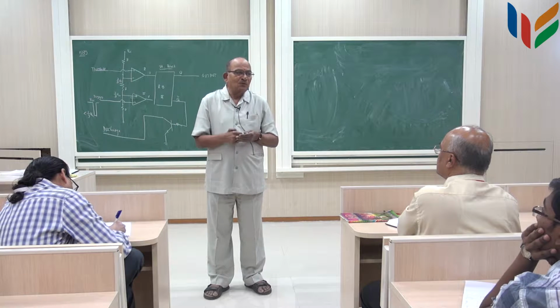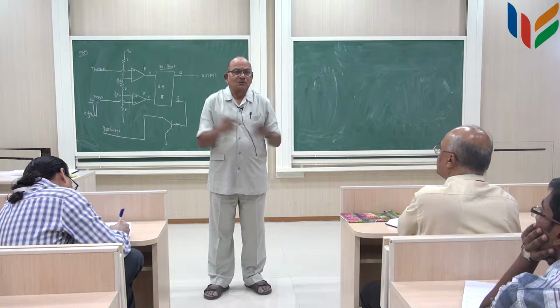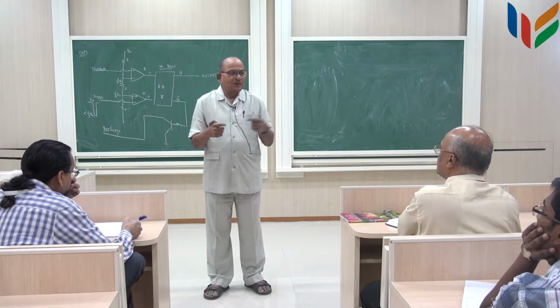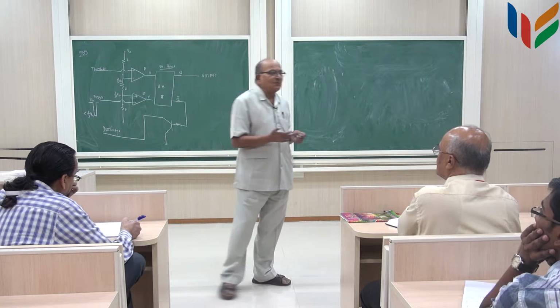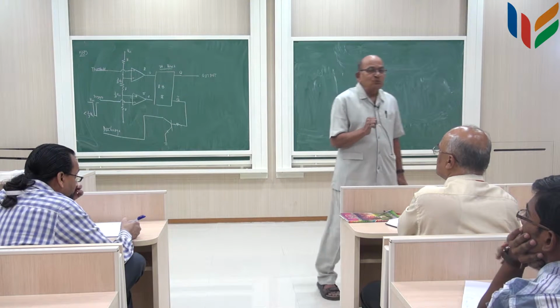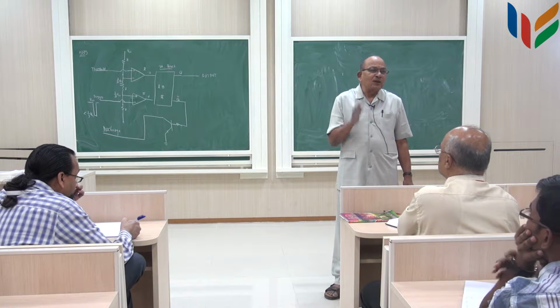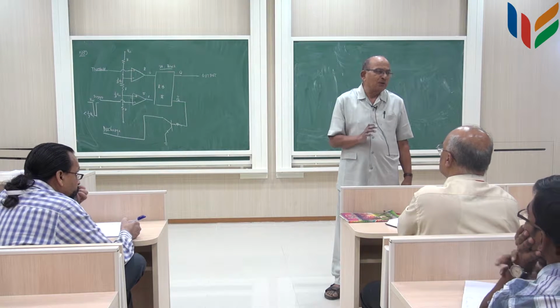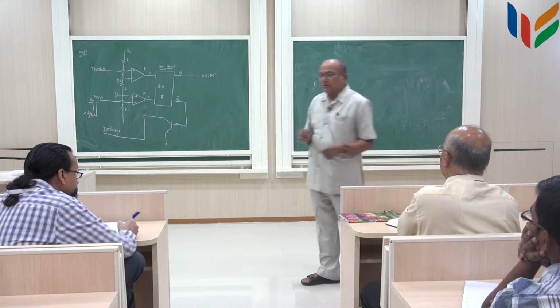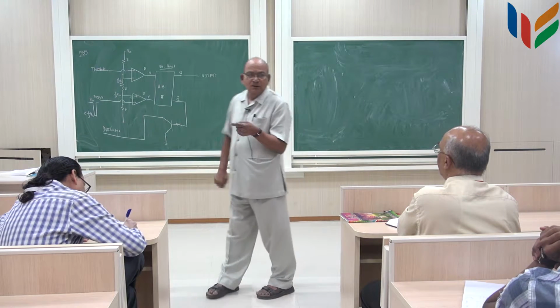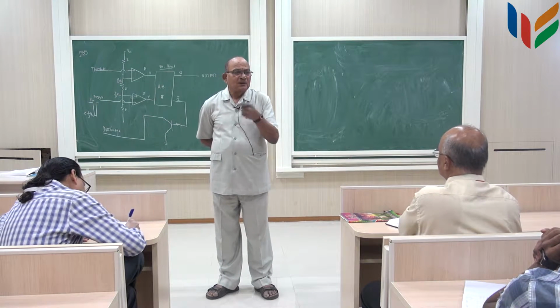I also would like to know how to multiply two signals, because that is also an important mathematical operation. So, I need to learn how to do multiplication. We have studied that also in the case of the difference amplifier, where we said that we apply one signal to the change in the current source and the other signal to the base of that, and approximately we will get a multiplication.